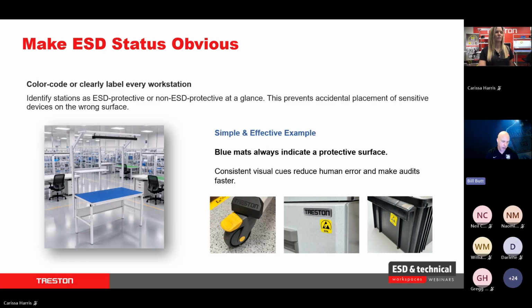If you've got grounded and ungrounded blue mats throughout your facility, that's going to create issues where people think they've got a protective surface and they don't. So that's a very obvious one, but very common to find that issue.